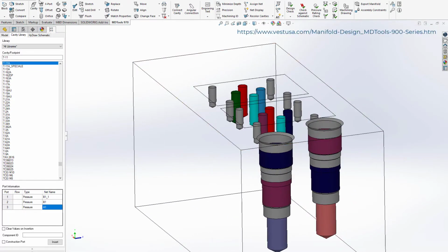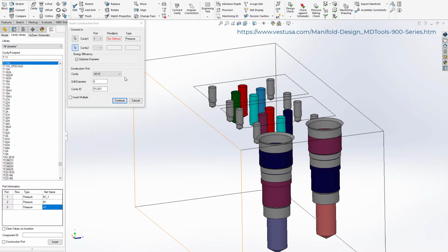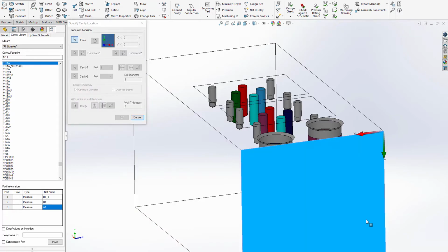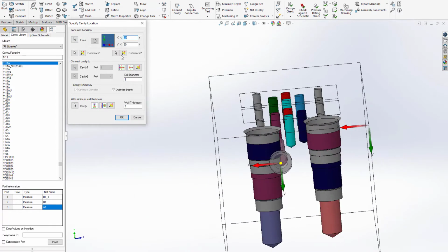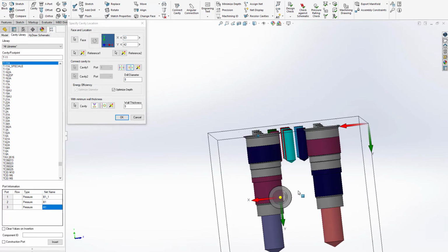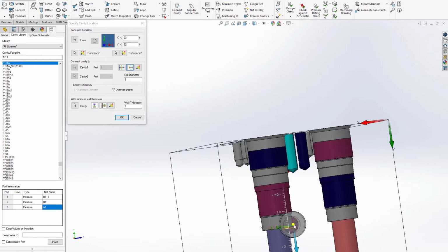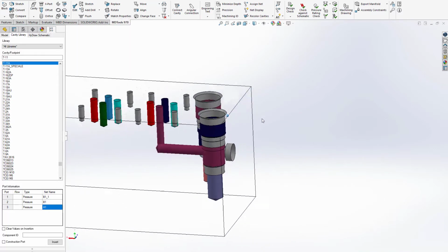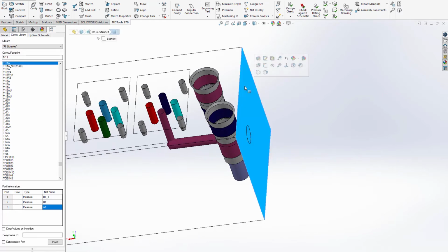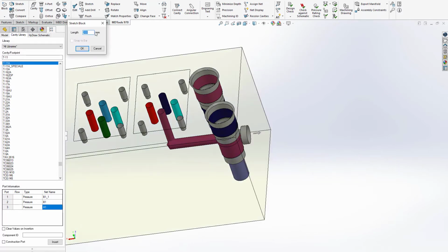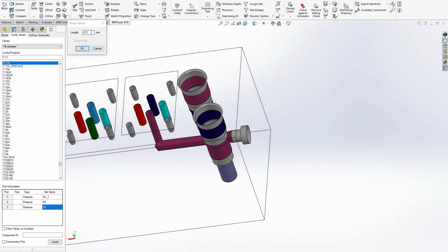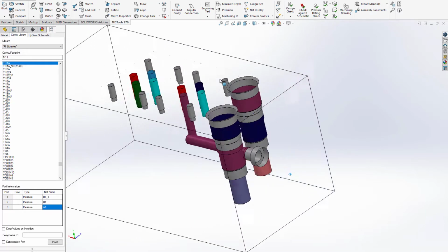Run export command. Touch EV1 port B and select the XG1/8 size. Click Continue, touch left face, adjust position and click OK. Select left face and stretch it, adding 10 mm and click OK. Then we connect the EV1 port A with CB1 port 2.